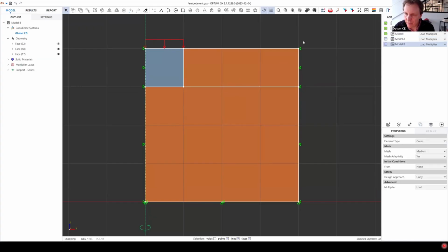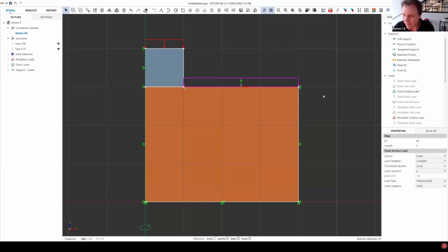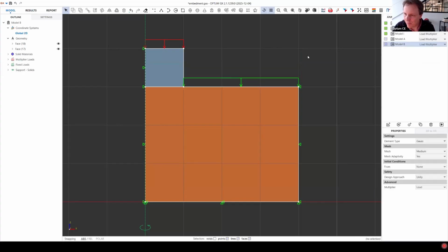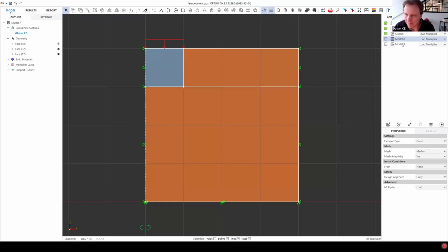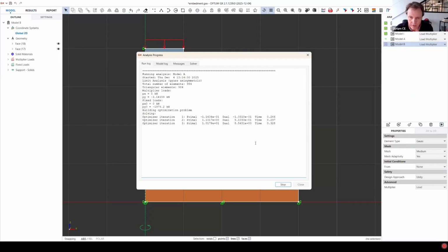And then we have sort of an approximate model where we take the surcharge into account, but where we have no soil up here above the base of the foundation. And this is a circular foundation. You can see I've turned on axisymmetry. So let's see what happens.